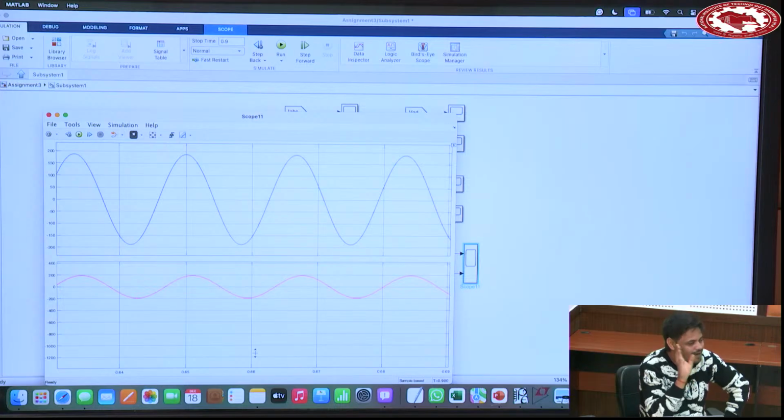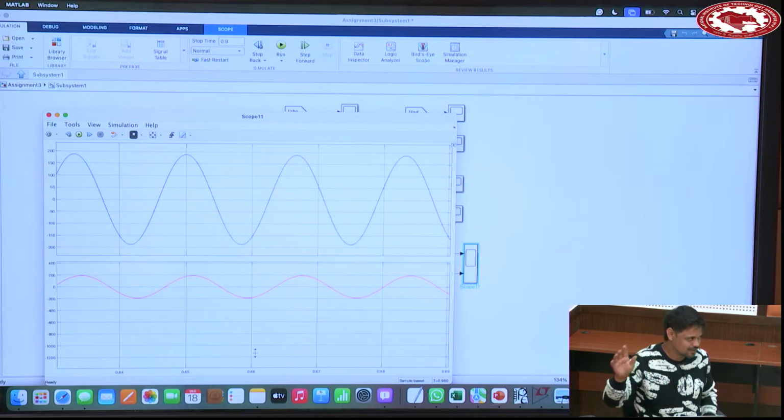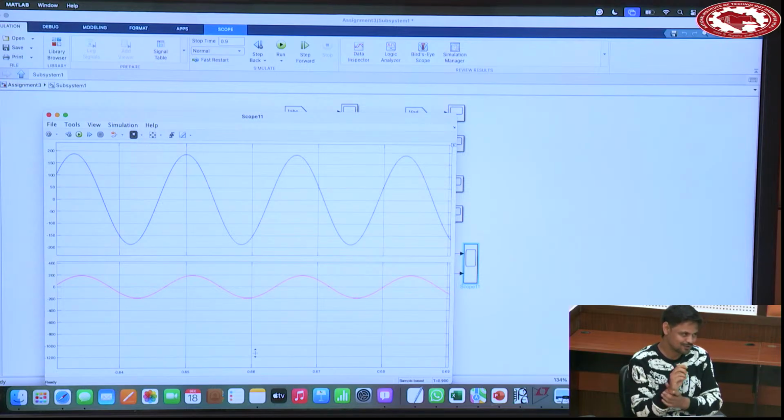You will not be having a battery. You will be having a load. You will be having a DC link capacitor. That time you will have to add one more loop to maintain that DC link voltage. I have that simulation for a subsequent day. I will come to that. I have touched the current controller today. I will touch the voltage controller and current controller combined in subsequent sessions. We have surprises for you.